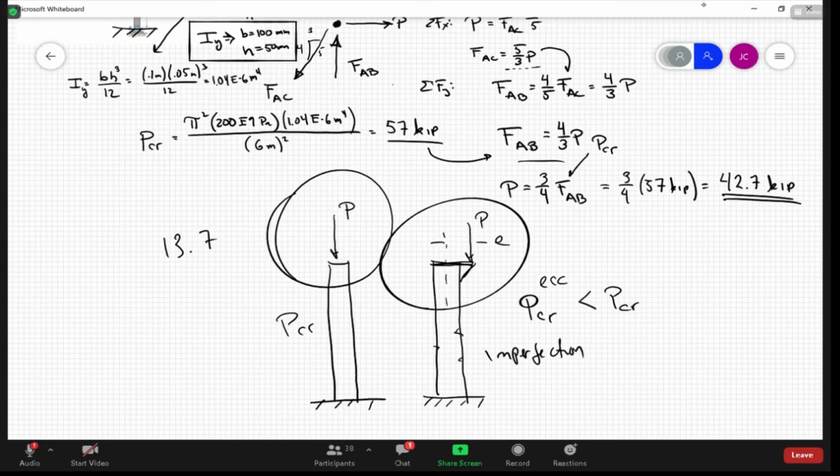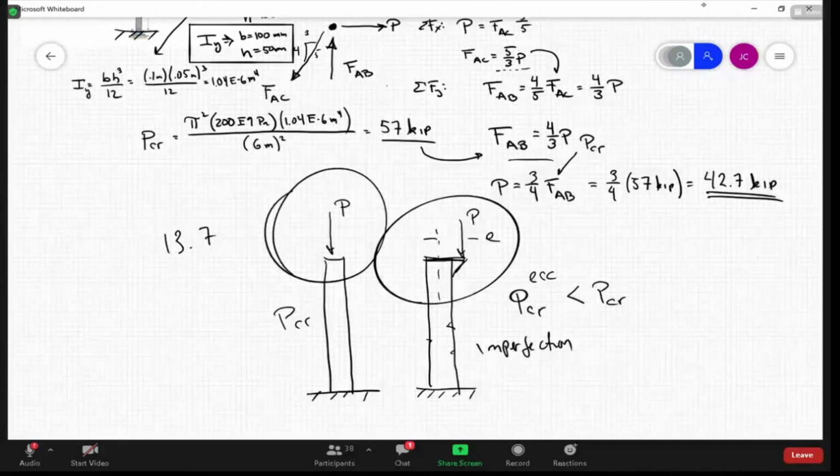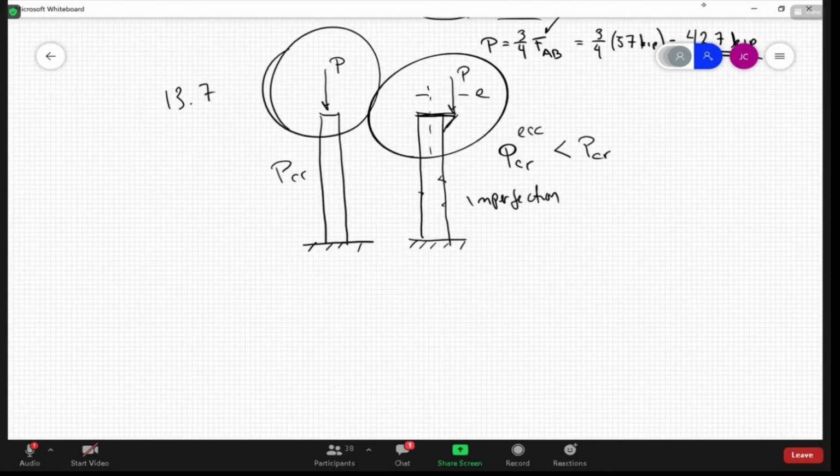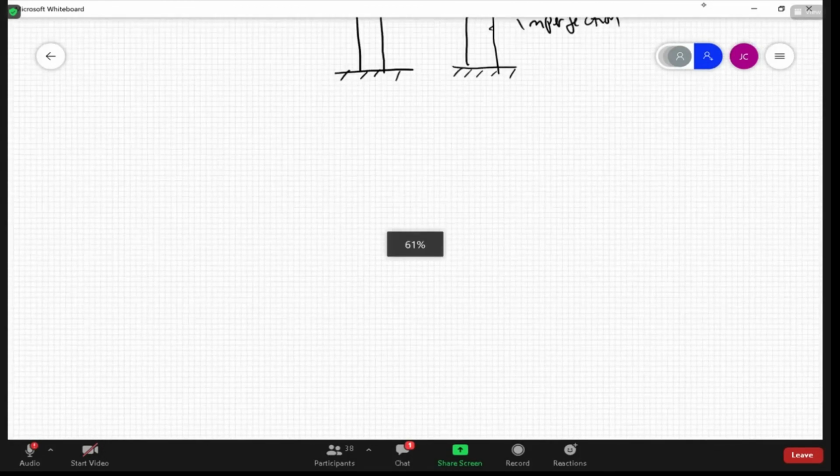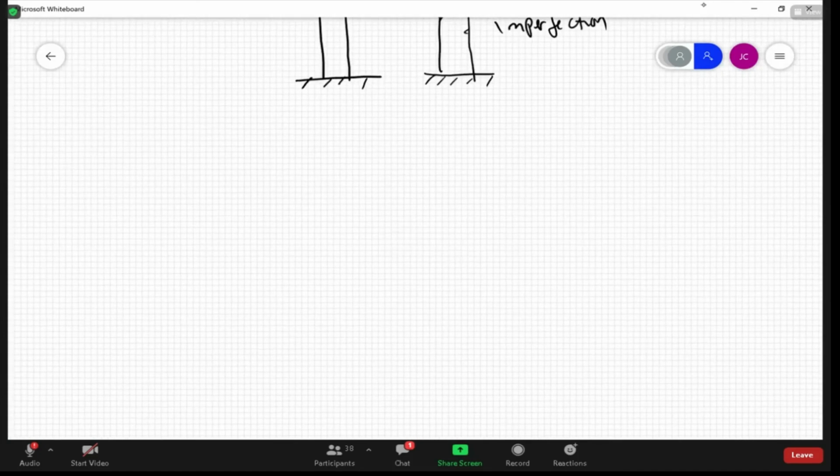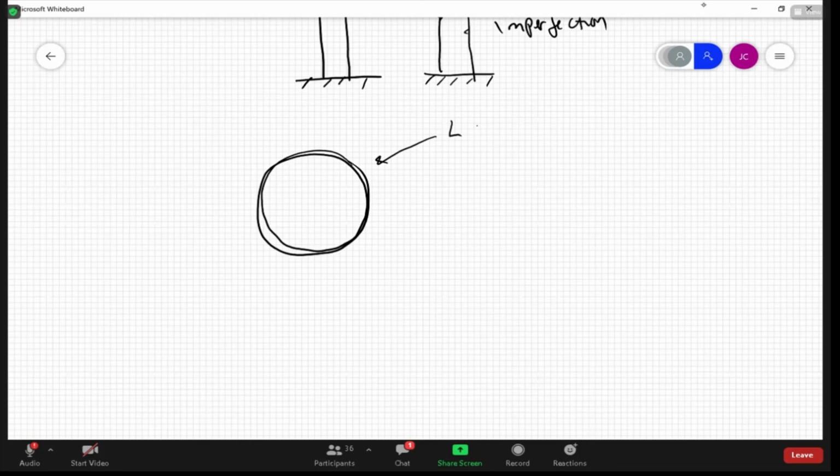Another classic example of buckling, and I can talk about this because we just went through it this week. One of the research projects we have is designing a lunar lander for NASA, and we have propellant tanks that hold liquid oxygen and liquid methane. Let's say this is the liquid methane tank. To keep them liquid, they're under pretty high pressure, about 400 PSI internal.